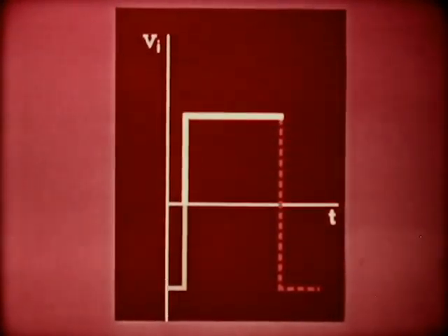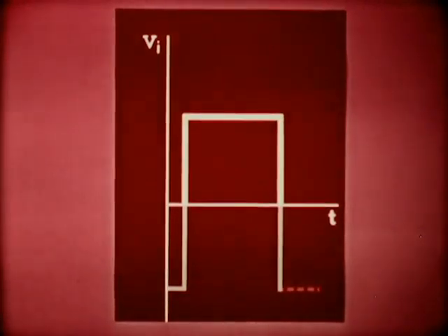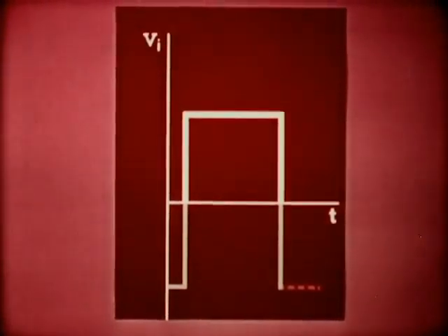Now let us see what happens when the transistor is again switched from saturation to cutoff. The electrons are drawn out of the base and the surplus holes quickly disperse. The level of the concentration curve drops to a point where the collector base junction again becomes biased in the reverse direction.